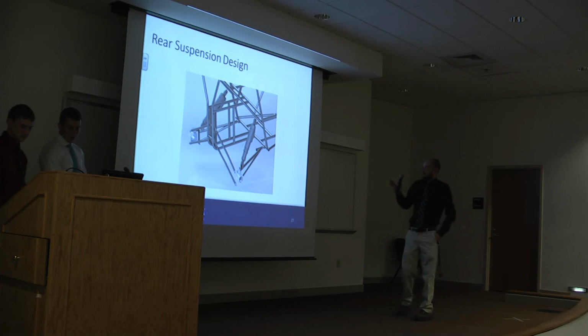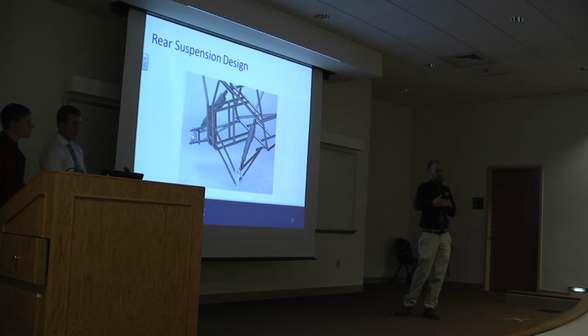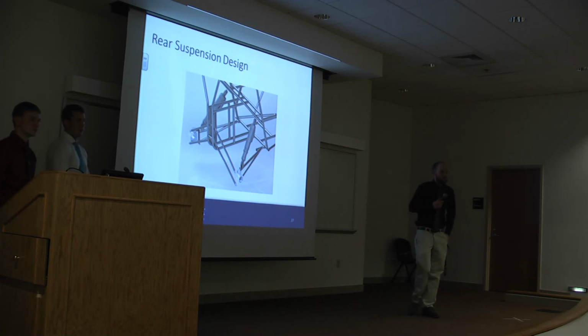Well, in that design, we've got a Heim joint at the front of that trailing arm, and that Heim joint will allow for that to rotate freely, and it's actually got up to 22 degrees of travel before it ever starts getting in a bind. Okay, I missed that part of it, I thought it was a fixed angle.